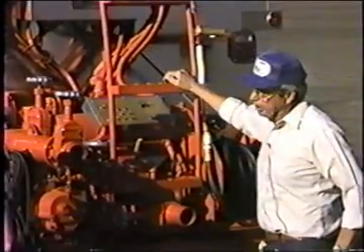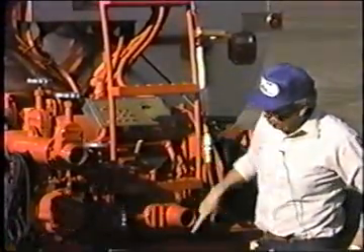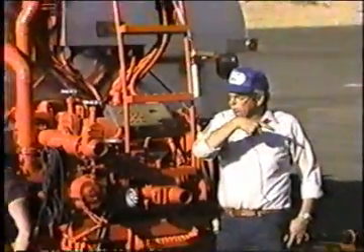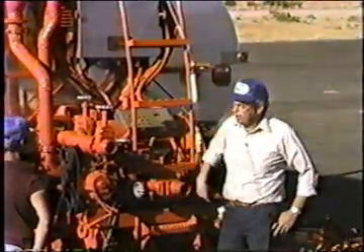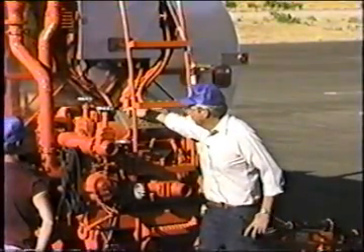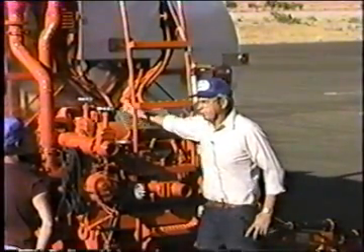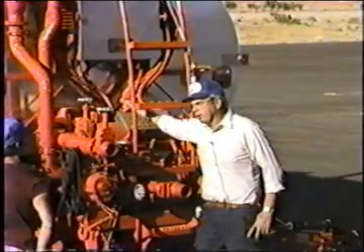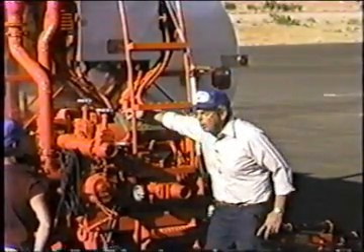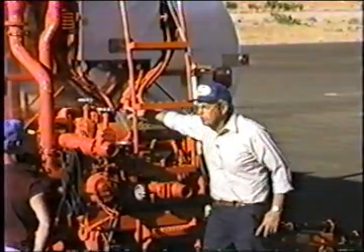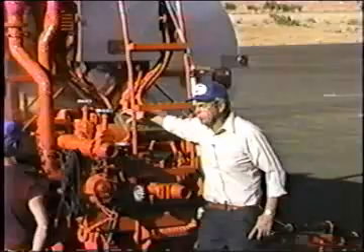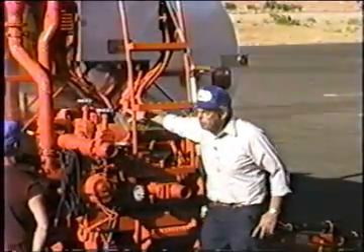The second reason is, let's say we think we have a plugged nozzle. We look in the mirror and we see a streak back there. We think we got a plugged nozzle, but it's underneath and we can't see where it's at. Well, come to the back, turn the rear master switch off, go back to the front, turn the front one on, now come back to the back, and you can snap the bar on and off. You can snap it on and see what's plugged up. You know, of course, you want to be backed off the roadway when you're doing this, where you can make a little mess, but snap it on, you can see which one's plugged up.